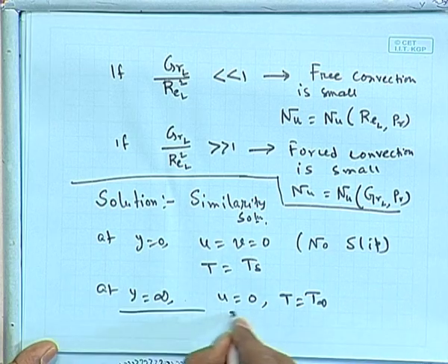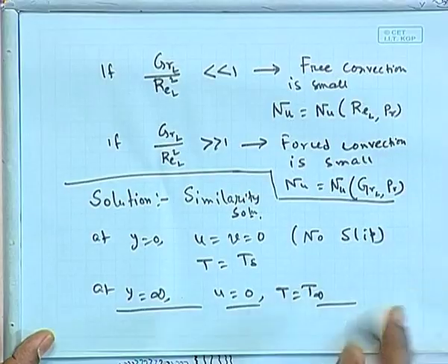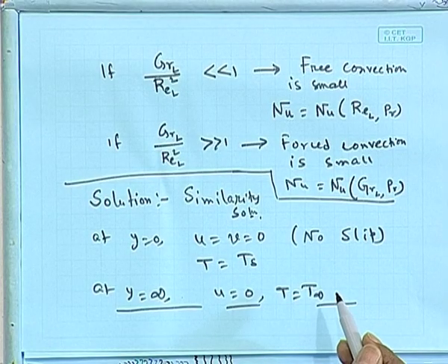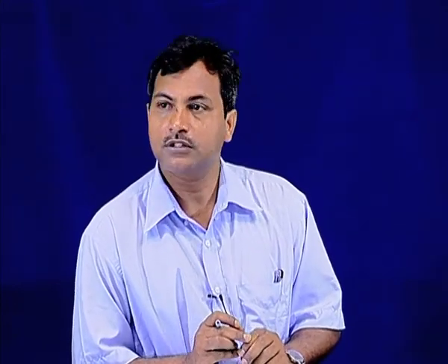Okay. So u and v both are 0 in the medium, which is stationary. Its resultant velocity is 0 at any point. If it is a two-dimensional flow field, what is the resultant velocity? Under root Vx square plus Vy square. That means both the components have to be equal to 0. At the edge of the boundary layer, velocity component in y exists, but it will be very small, because of that entrainment occurs. Otherwise, it will be very small.